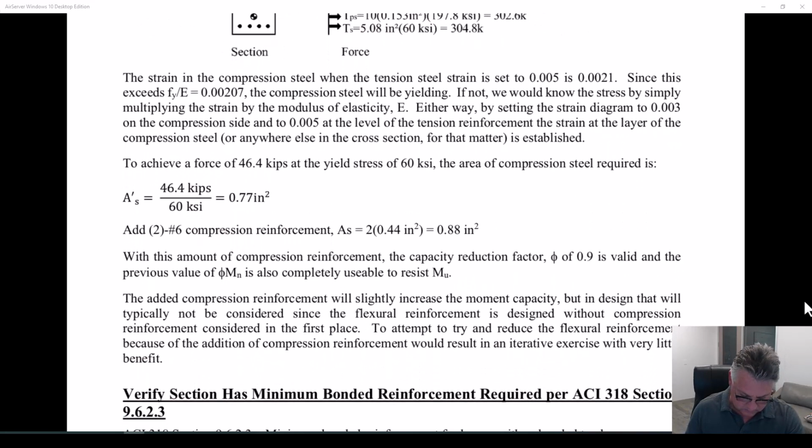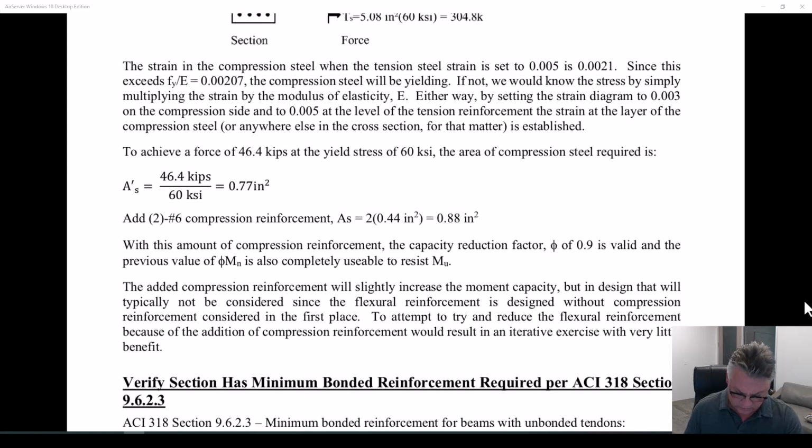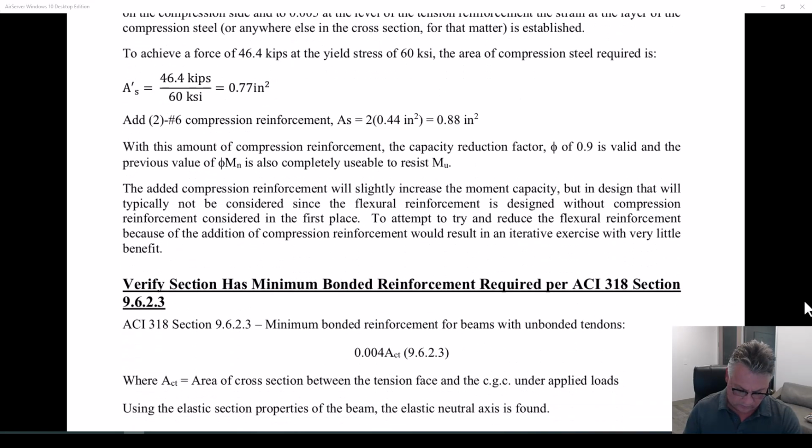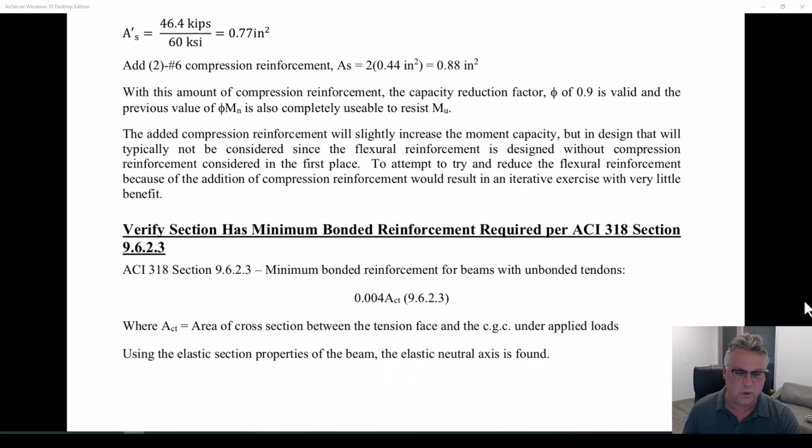And that, kids, is where compression steel comes from. So I'm going to make sure that you do this on one of your homework assignments. Provided that we put that compression steel in, we're always using a phi factor of 0.9. So always, always, always the phi factor is 0.9. There's never any reason to play with the equation in the code.